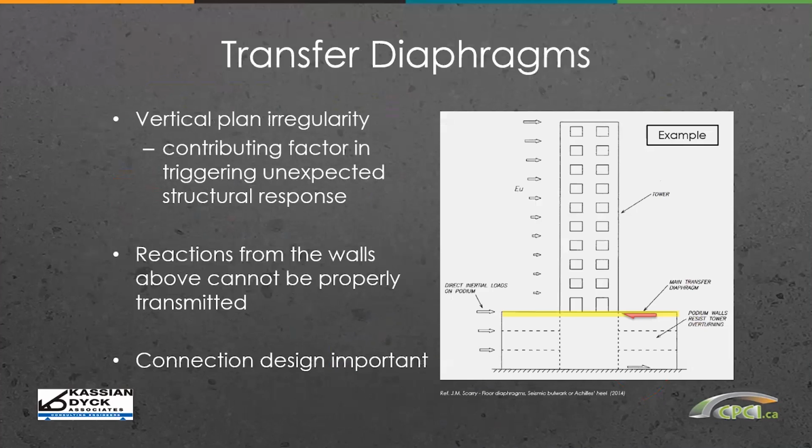If you have rigid, stiff connections and you're connecting it in, then it's going to want to transfer that force into your main floor diaphragm, and you'll have to design it appropriately, and that'll change the shear and the moments and your design of your shear wall, because now you have a very large reaction at that main floor or podium level that's taking shear out from the shear wall above, versus if that was not connected or had soft connections somehow and carried straight through down to the foundation, then it may be a cantilever going all the way down to the foundation level.